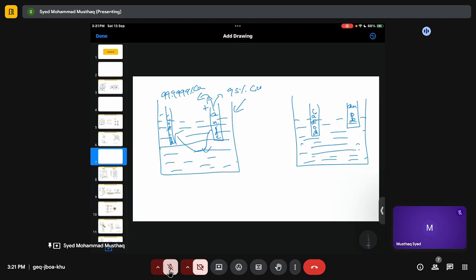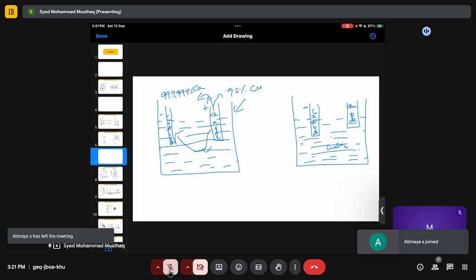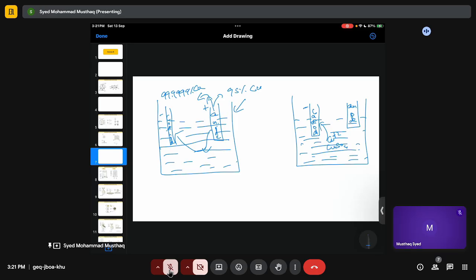And the other way is you have a copper sulfate solution, you dissolve everything into a sulfate solution or any type of solution, nitrate, chloride solution, and then you apply negative charge here, and whatever copper was dissolved in here will get deposited. So the only difference is in electrodeposition, the ions are coming from the anode. In electrowinning, the ions are coming from the solution. Okay, so that's the only difference. There's no great physics in there.